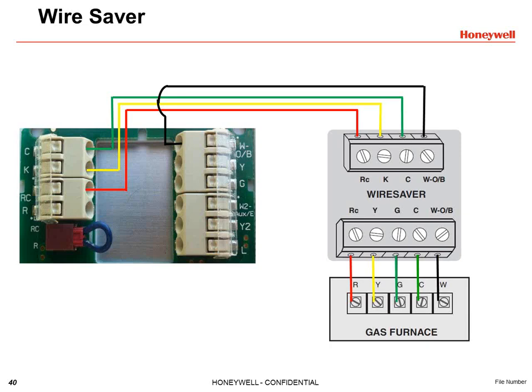Yeah, this particular one you have to use on Honeywell products because the stat has to have a K terminal on it, as you can see on the left-hand side over there. We have another one from Ventstar, which we'll talk about later if there's enough time, that we can use on any thermostat that we want. That's a typical Y, G, and so forth. So with this wire saver for Honeywell, you have to have a K terminal like you see over on the left side. Basically, the K terminal is a digital signal that represents both your cooling and your fan signal. So if you look over on the right-hand side, the wire saver still has your common wire, your R wire, your W heat wire, and then you have this K. The K gets divided out into Y and G later on.